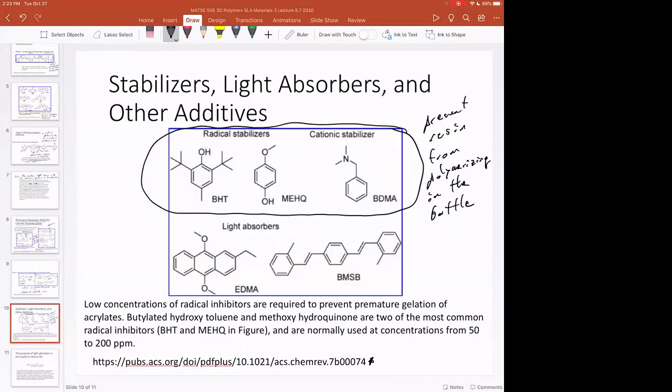And so these are reactive molecules. The epoxides and the acrylates and methacrylates are ready to react. They'll react under thermal conditions. So if you ship your resin to Phoenix, Arizona in the summertime and it sits on your porch for a day and it's 120 degrees Fahrenheit outside, that could certainly have an adverse effect on your resin.